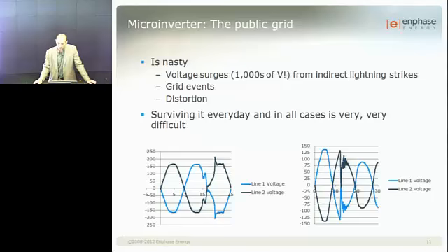I assume you're asking why other appliances can take that. Well, if you look at most power supplies, usually on the front end you have a diode bridge, and then you have a capacitor, either directly or indirectly behind an inductor. And this big capacitor is really good at absorbing some of these problems. Well, in a DC to AC conversion, we don't have anything like this that self-protects the unit.